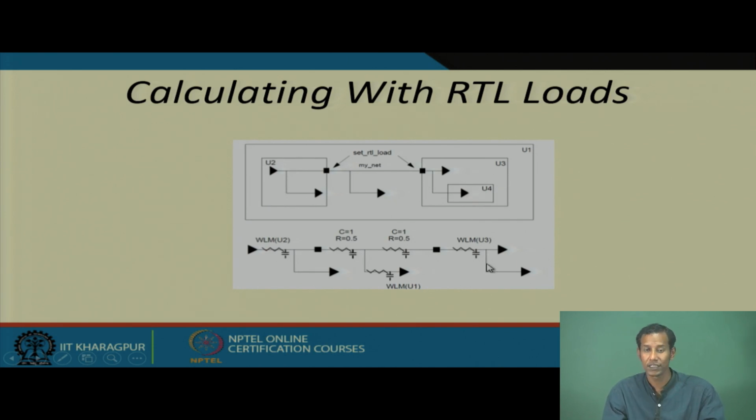Based on this, a SPICE simulation runs in the background and calculates, for this configuration, for these capacitance and resistance values, what the corresponding delay for this particular path will be. Depending on the corresponding loads, the capacitive load changes this value. So depending on the calculation, the value will be reflected in the timing analysis report.